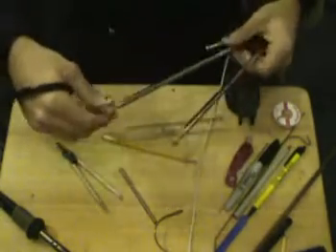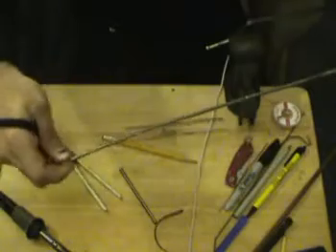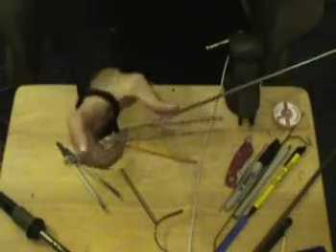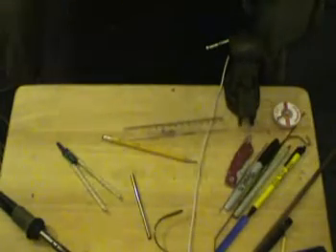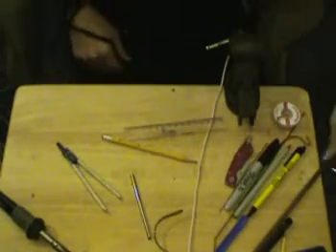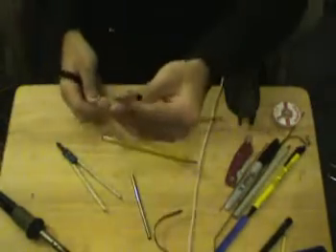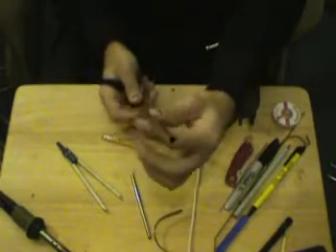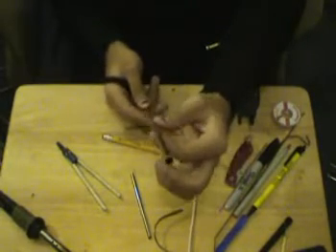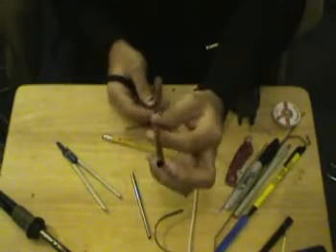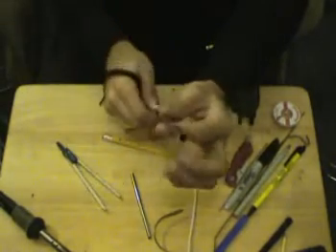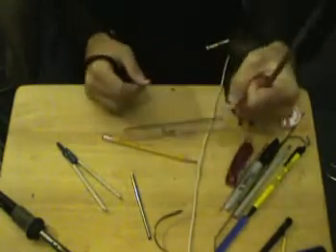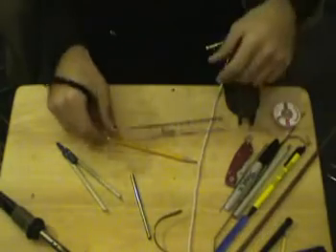Well, of course, you can't use this antenna as is. So what I did was I extended it, and I just cut a segment out. And that's where this tube came from. This literally came from a leg of an old TV antenna. Now, you might actually have something else laying around the house. Like you can go to the hardware store and buy a brass tube. This tube actually has the exact outer diameter and inner diameter, so you can feed LMR 195 coax down this hole. So this would be good for a really nice, sturdy antenna.